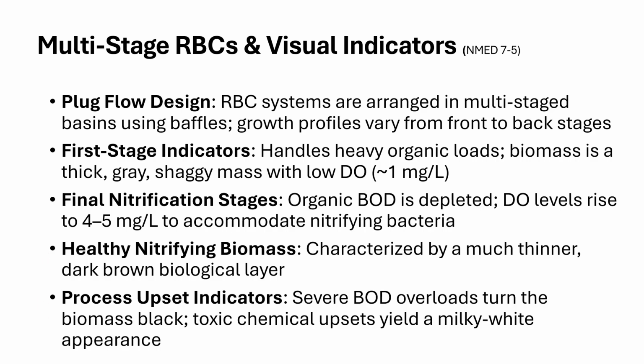If we have an upset, so if we have a huge amount of BOD coming in, the biomass can turn black, and we'll get a toxic type of chemical to the microbes, and it'll get an upset, and we'll get a milky white appearance in our wastewater there.